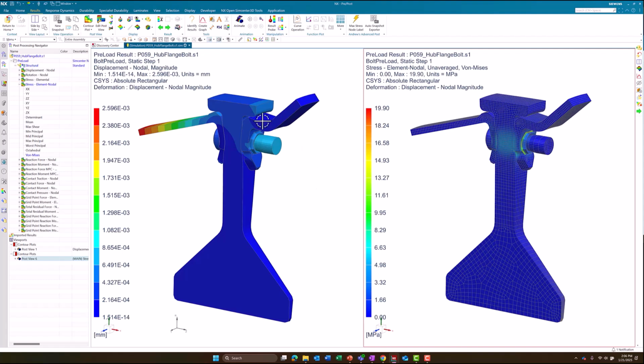Next, we'll look at display attributes. So the couple of display attribute differences I have here. On the left, I'm looking at a banded display and just the external edges. And on the right, you have a smooth display with the external edges and the elements being shown, right? So if I right click and choose copy viewport and then paste special, I can do display attributes for my paste special, and we'll see that now we're getting those external final feature edges, the same as on the left, and we're getting the banded display as well, same as on the left. So any of the display options can be copy and pasted between them.